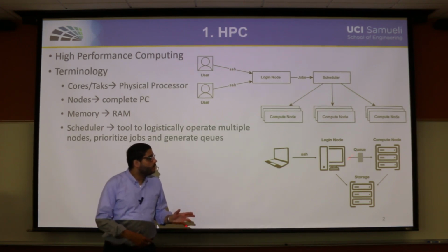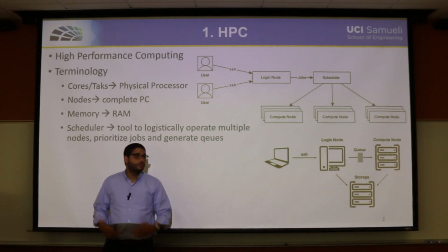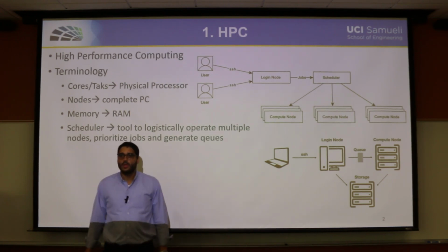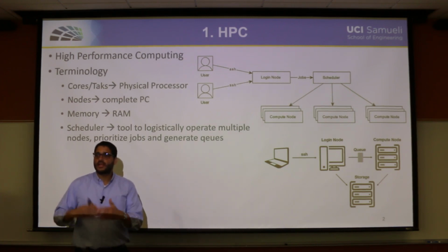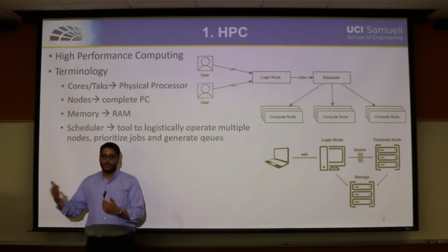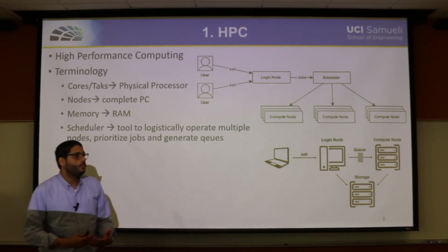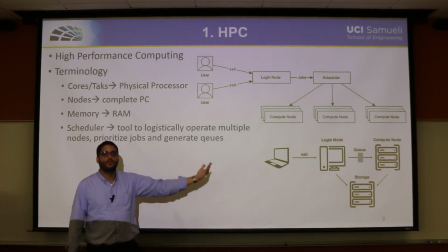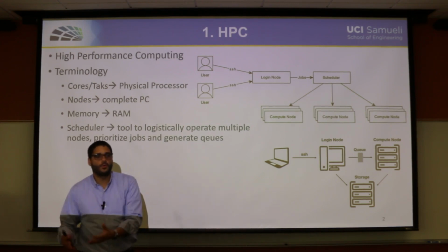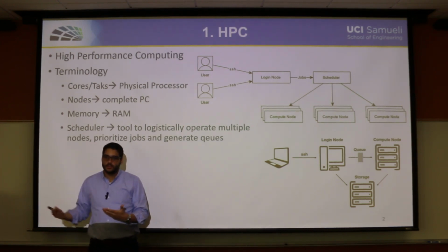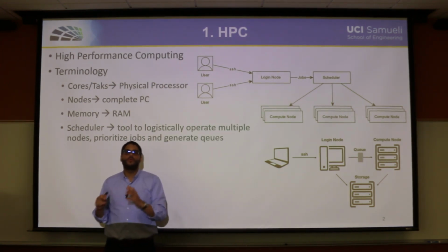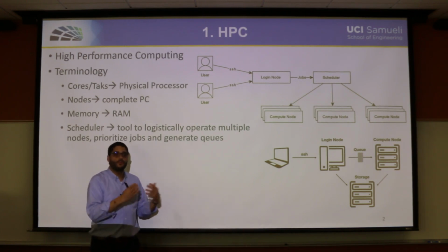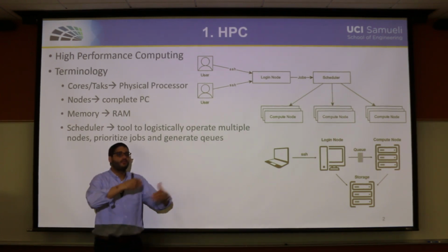And if you are logged in on the login node, you will find that you can access those compute nodes in two different ways. One of them is called interactively, and the other is batch mode, or background mode. What do we mean by that? If you are trying to compute something that requires some interaction from you, as if you are using Fluent software on your local PC, the HPC allows you to do this, but for a small period of time and with small hardware capabilities. In other words, if you ask the HPC to give you an interactive node, you can open your case file and do everything interactively online.